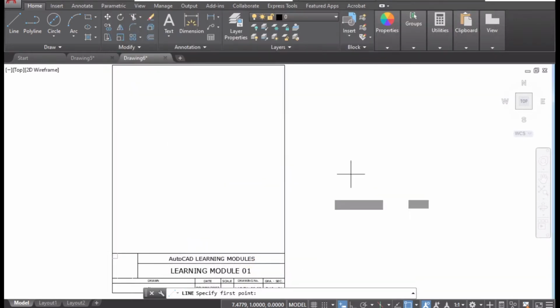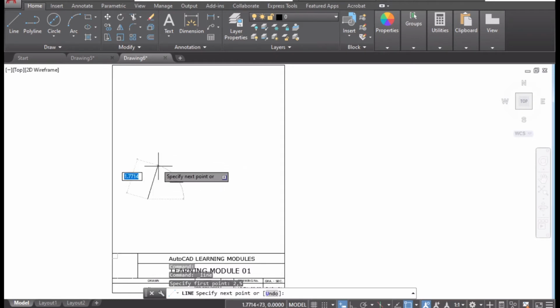Here I would like to mention certain settings in AutoCAD that you're supposed to turn on before you begin this activity. Right now when I choose the line, you can see the coordinate boxes are coming. Here I can put my coordinates, x equal to 2, and if you want to jump to the next, you can either hit comma or tab on your keyboard. I'm going to use comma, then 5 or whatever you want to enter. When you put the coordinate and hit enter, you can see your points start from that particular definition.